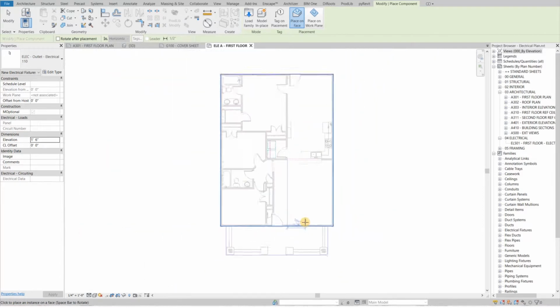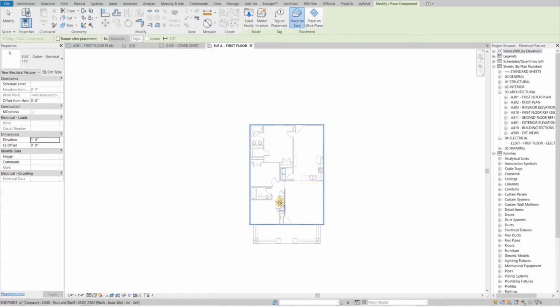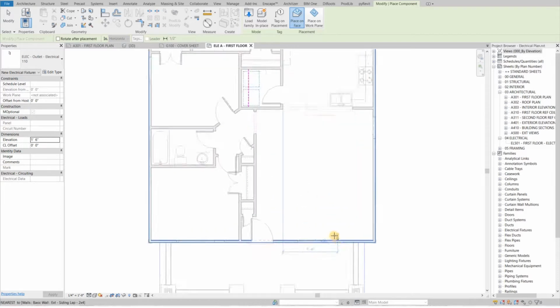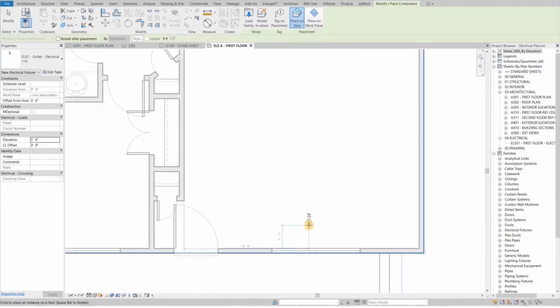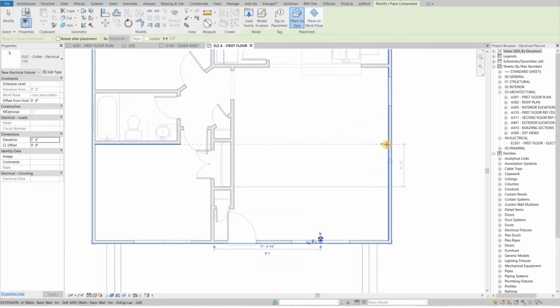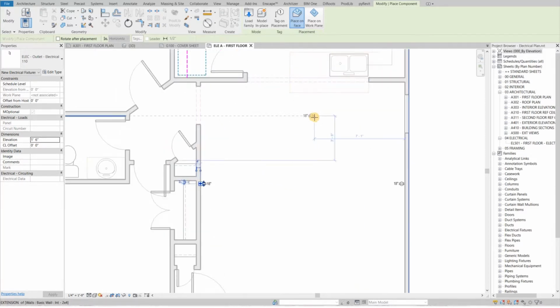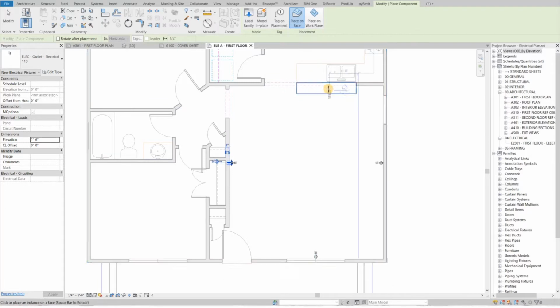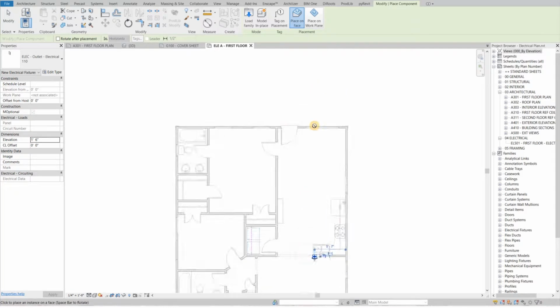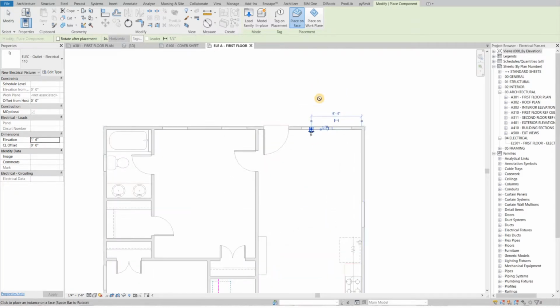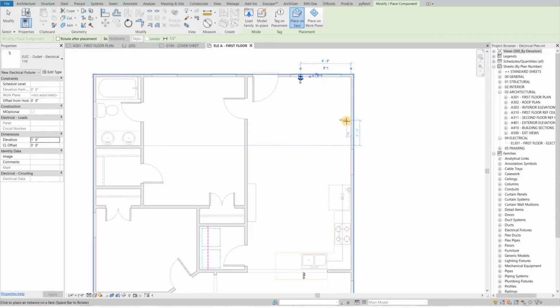So we're just going to cover the living area, kitchen, and one bedroom and toilet area. We're not going to cover the whole house. So okay, for this living room, we're going to add outlets here, like this one again at 18 inches, and there will be one more. Oops, sorry. Yeah, here at the center of this wall. Okay, and for this side, same. We can do it at 18 inches for the dining area.